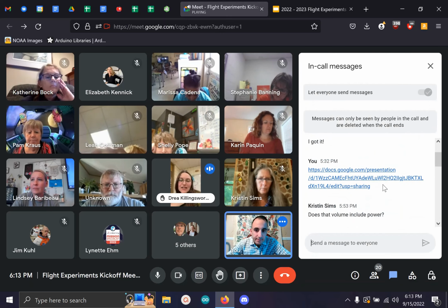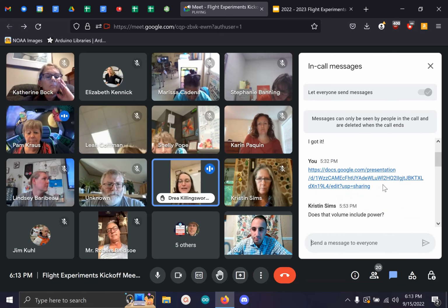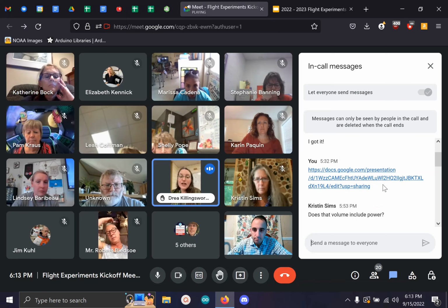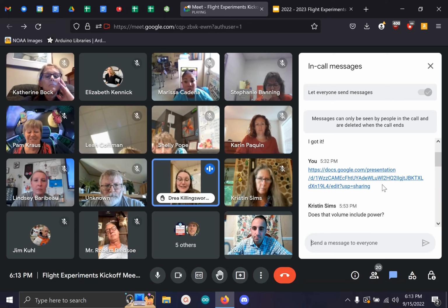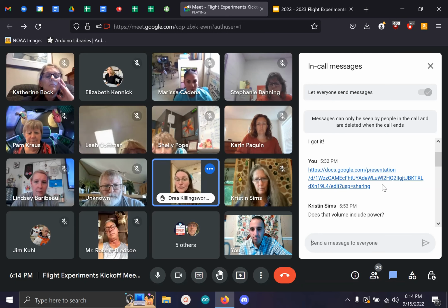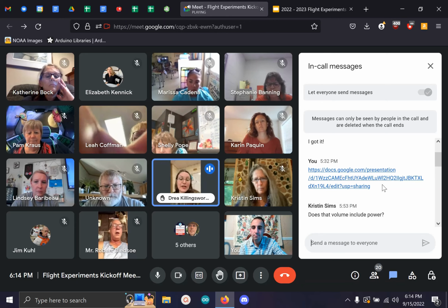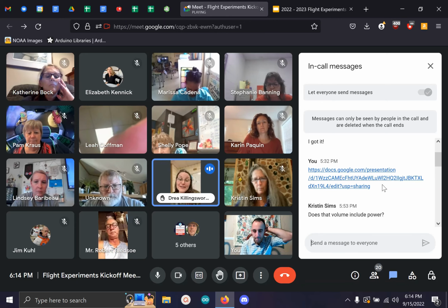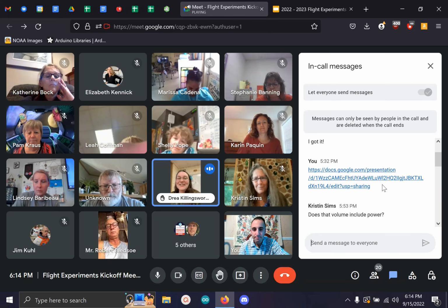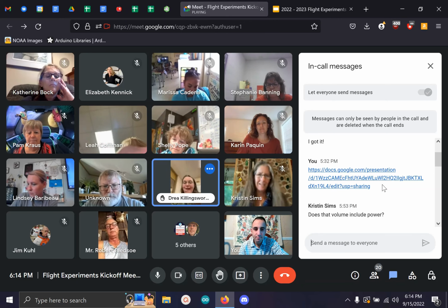All right. I was going to say, because we used Nano Everys for BattleBots last year, just to warn people, they are very sensitive. If you have students who are new to Arduino and they're not grounding things, they literally catch on fire the second they plug in. But they have the same exact configuration as an Arduino Uno. So you could have students build on an Arduino Uno that is less sensitive, just so you're not replacing all your equipment.